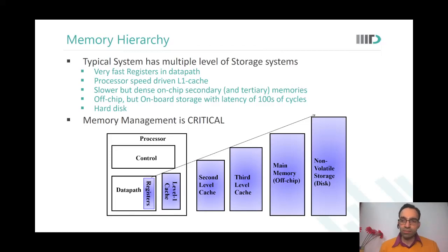Power consumed also means heat dissipated. So if the power consumption is very high, then I also have to put in place sufficient mechanisms to remove that heat from the system. If you have a very high power consuming system, you will have to have complex cooling mechanisms like liquid cooling.